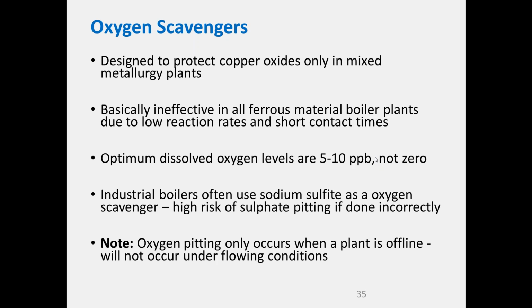If you've got copper materials in your plant, then yes, you do have to dose an oxygen scavenger, and that oxygen scavenger is actually to protect the copper oxides that form on those copper materials. So if you're all ferrous, if you look at your material sheets and you say, I've got all carbon steel through my whole plant, or I'm stainless steel, and you have a deaerator, and you're dosing an oxygen scavenger, I'll give you some advice, which is you don't need to dose the oxygen scavenger, okay? And you actually want 5 to 10 ppb of oxygen, you don't want zero.